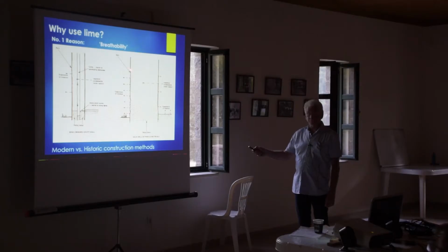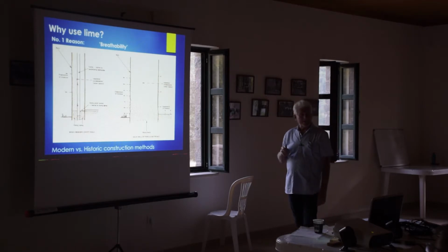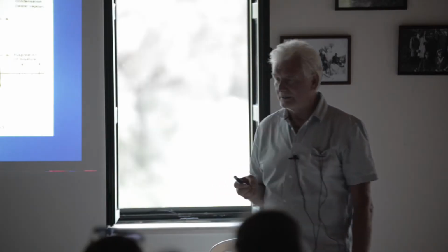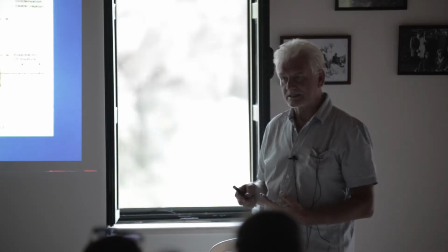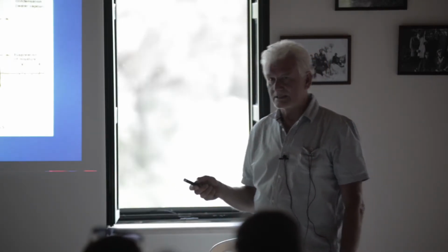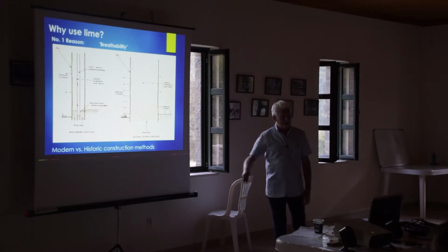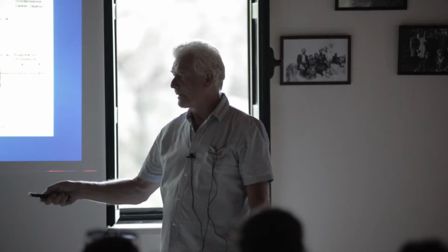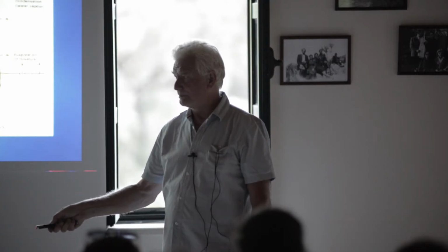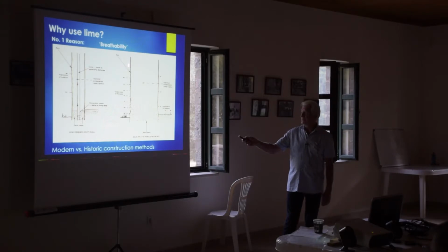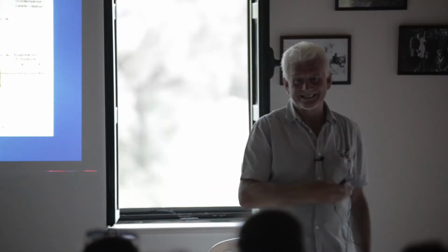The water would come to that point, it has nowhere to go, so it comes back in again. And that's why you often see walls in older houses where you get particularly damp marks at the top and rising damp at the bottom, in combination with the water coming up from the ground and the water being trapped within the wall because it can't go out. All it can do is come back in again.